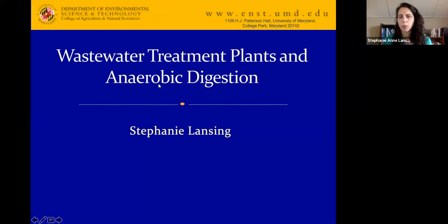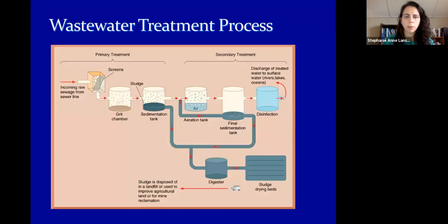Welcome to wastewater treatment plants and anaerobic digestion. So just a primary overview of the wastewater treatment process. It starts with primary treatment. The incoming sewage gets in, you get out the grit, the sedimentation, what settles goes, it could go into a digester, it could just go straight into sludge drying beds, and that biosolids then gets